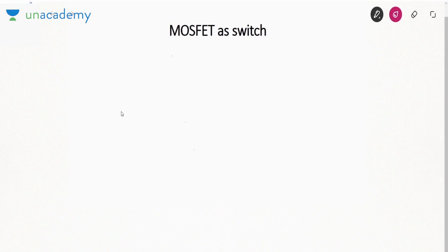Hi guys, in this video we'll be discussing other applications of MOSFET. That is, we will be studying MOSFET as a switch so that it can be used in digital electronics as well. Okay. So why do we use MOSFET as a switch basically? I told you when we operate MOSFET in the saturation region, then it is basically acting as an amplifier. So it means if we operate it in the cutoff or the linear region, then we can operate it as